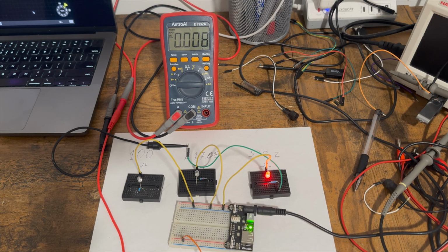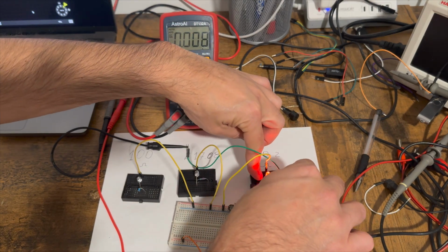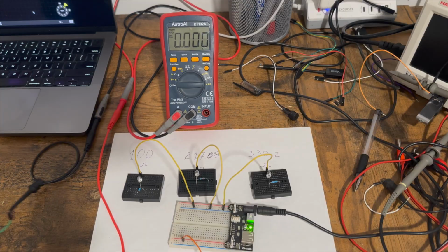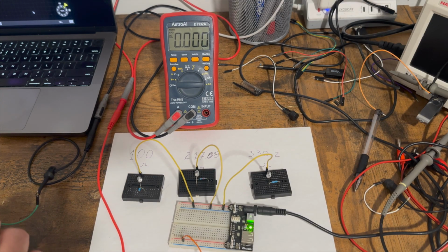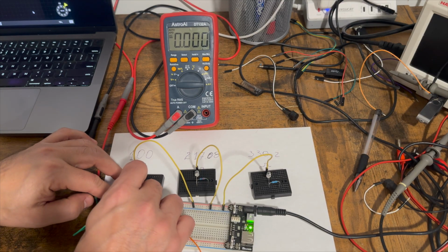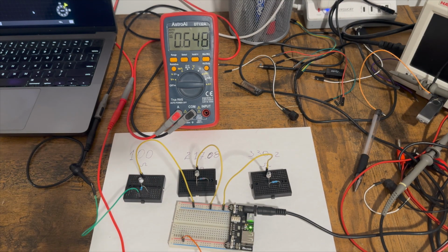So now let's do our final experiment. I want to show you what is going to happen if we don't use a resistor. So this is the resistor side, and the other side is bypassing the resistor. I'm going to put my 5 volts in here, and let's see what's going to happen. We are drawing 600 milliamps. The LED is not even shining and is burning. At some point, it's just going to stop drawing current, and that's pretty much it. The LED is gone. So that's the reason we put resistors before LEDs, because we don't want to draw more current than the LED is supposed to.